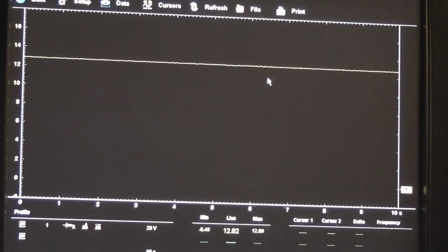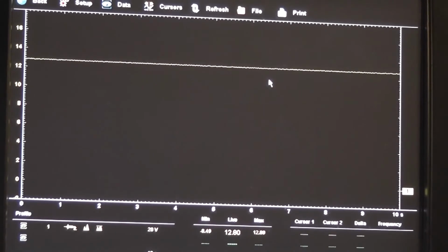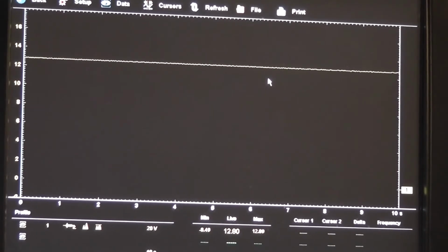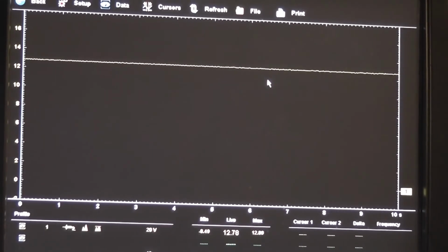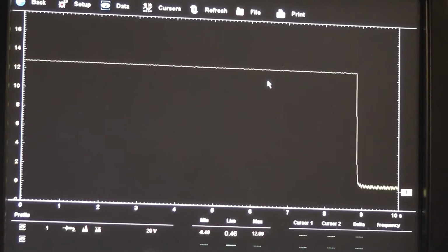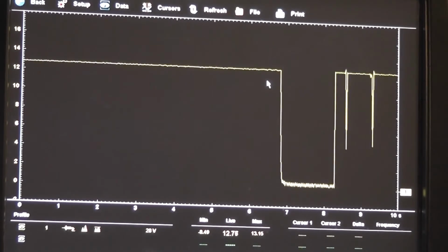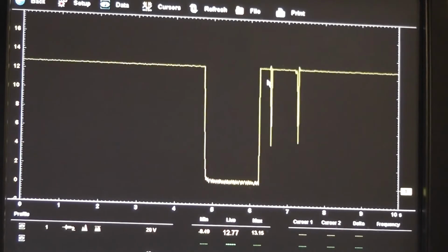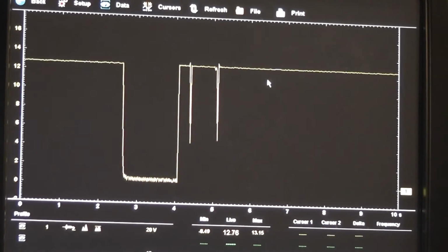Okay, with the new solenoid installed, we have the key back on. We're going to retrace some of our steps. We're going to do our 2 voltage measurements first. This is on the wire to the right, which is our feed wire, and you can see we have battery voltage on that wire. Disconnect my T-pin from there, put it into the control wire, and now that we have a good solenoid in place, you see that we have 12 volts also on the control wire.